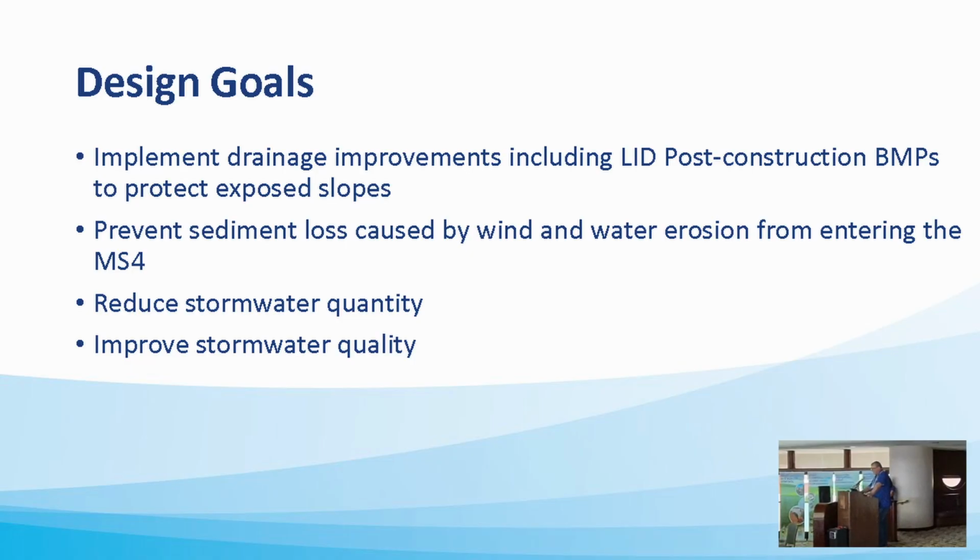The site was split into separate parts to maintain drainage patterns. The surrounding grades and proximity to the existing fence and utility poles constrain the overall size and general shapes of the basins. Due to the high volume of runoff, riprap aprons were proposed to help provide energy dissipation for incoming flow to each of the bioretention basins. A vegetated swale was designed to help convey the flow to basin number 2 due to it being a longer distance away from the high point.